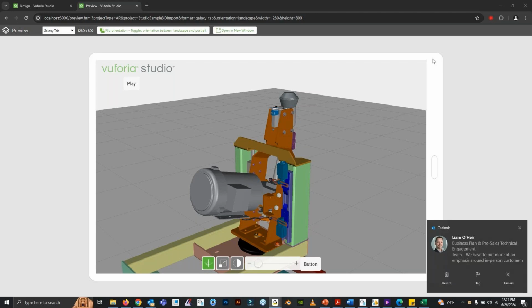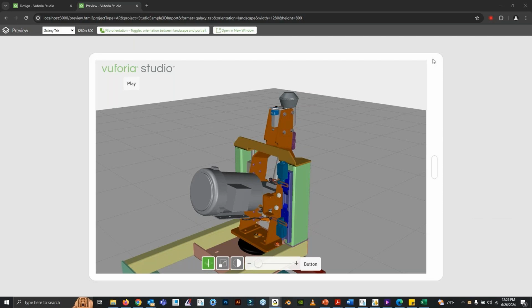So if you change a dimension, usually it's a dimension or the size of a cut or something like that, you do also have to go back and change it at the part level, save the part, then re-export the assembly. But after you reopen Illustrate, and that's the importance of that link option, when you go to import link, it's maintaining that link between the CAD data and the illustrations. So you do not have to redo all your images with a new revision. It will automatically update through the images.